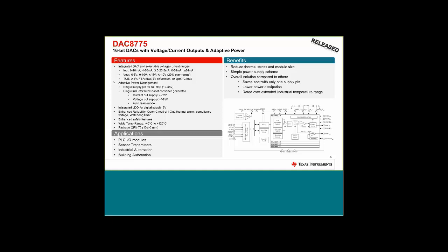So barring some kind of compliance voltage condition, if you were to try to drive a load that's too big or drive too much current into a large load, you'll always see the desired output current across the load. Clamp mode kind of changes the operating corner a little bit, basically by reducing the minimum voltage that the DC-DC would output. So suppose you're using this device with known loads and known maximum output currents, and you don't want to deal with full tracking mode. You would just set this clamp voltage and it would maybe never change.